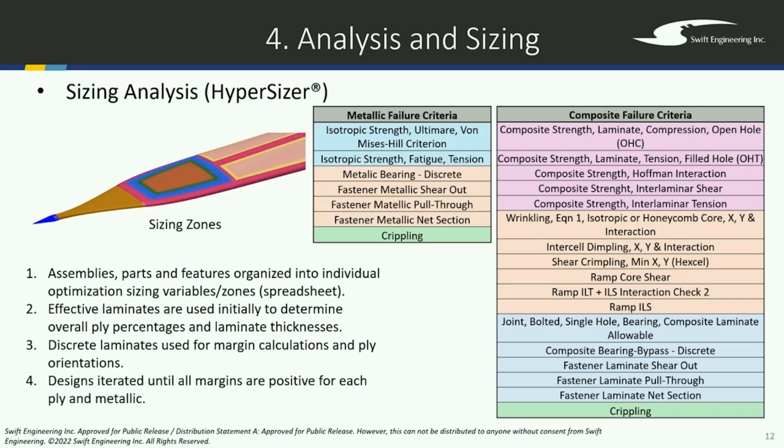So these are some of the real challenges that you come across when somebody comes to you like this. And it was good that they said, yeah, you can make it however you want. They didn't have a desire to make it into 1 piece, or we could have made it into several pieces, but 2-piece main cone. So it had a top half, a left side and a right side that came together. So it's 4 pieces overall, but made into 2 main pieces. The main reason was our autoclave was just a little bit too short to make it all into 1 piece. 1 piece would have been preferable, but yeah, it ended up the way it is.